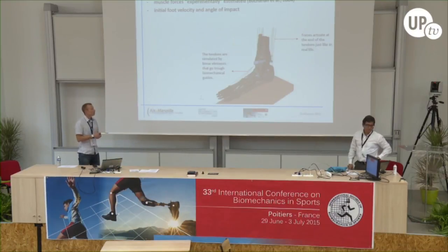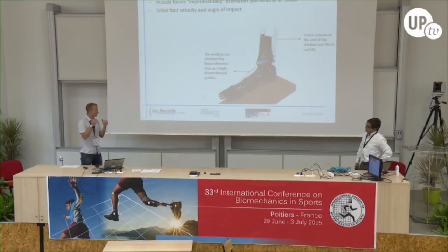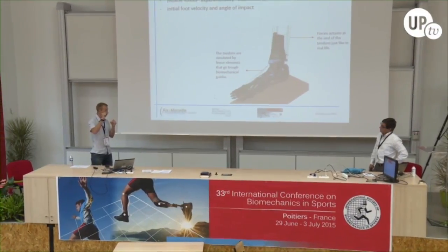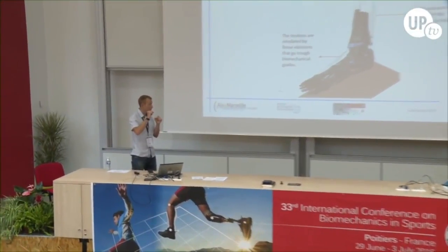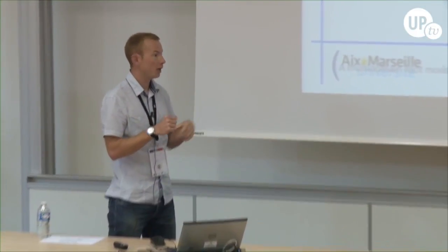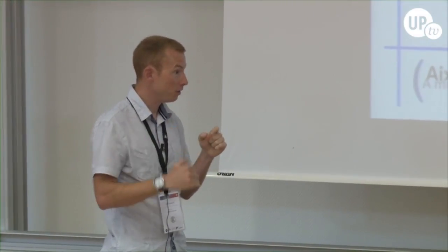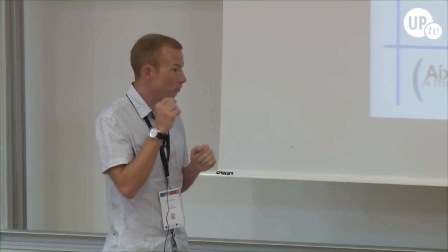So it's not an a priori contact model, it's just a penalty contact model where we don't allow the different elements to penetrate each other. But as we have all the mechanical properties of the structures, such as the heel pad, the muscles, the sole, and the ground, there is no need for a precise contact model.